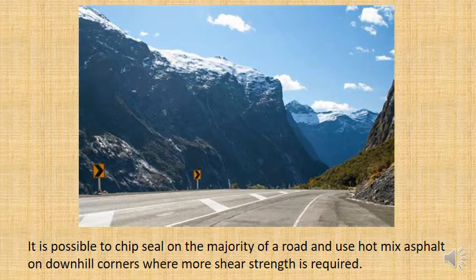Well, it's where there is the greatest shear force on the road. Where does that happen? It's where the road is going downhill and there is a sharp corner, because that's where cars are going to be going fast and the force of gravity is behind them, and then suddenly they're going to brake. That is going to shear aggregate out of the bitumen and the wearing course.